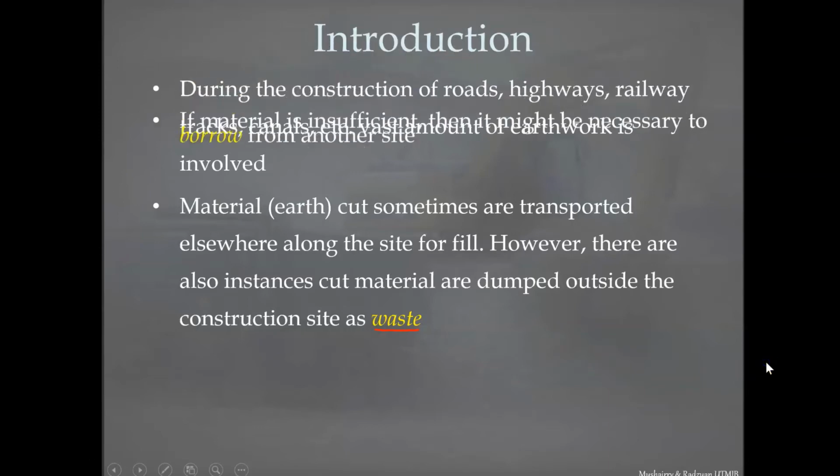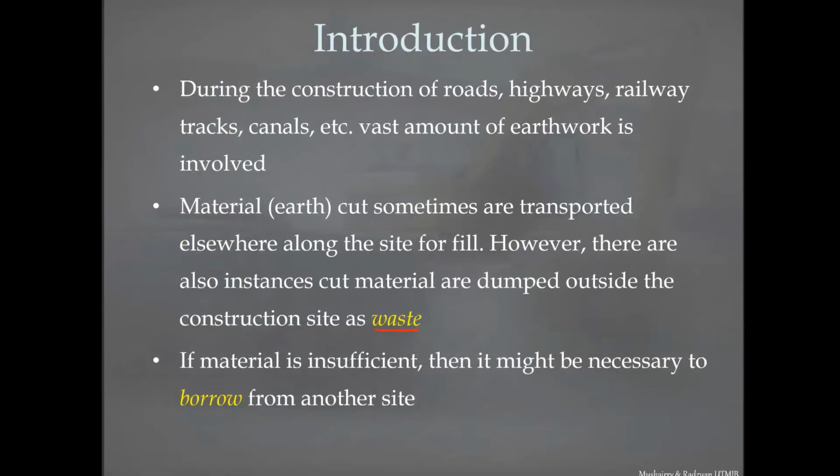At the same time, if we have a condition whereby an area needs to be filled, but there's no material to be found nearby, not from the construction site, that means we could take it from outside. We have to import the material from outside, and we term that as borrow. So borrow means material that we need but is not available at that site. And waste is material that is unsuitable to be used and will be dumped somewhere else outside the site area.